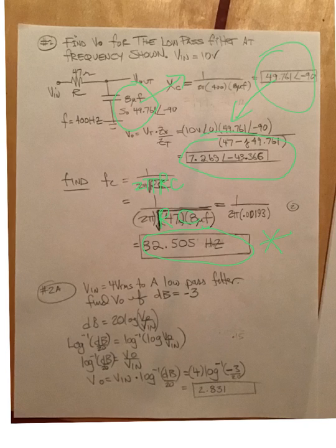Okay? And last but not least, I've got an input of 4 volts RMS going through a low-pass filter, and the output voltage drops minus 3 dBs. They didn't tell me how many volts it dropped. They told me how many dBs. Well, if that's the case, I've got to take the dB equation, which is right here, and do this thing that most of you, I can almost guarantee, don't remember.